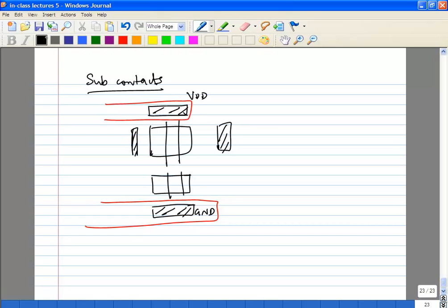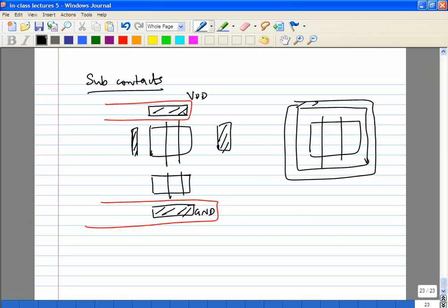However, every process, especially an analog or RF process, will have an RF transistor, which would typically have the transistor and a substrate ring around it. This transistor as a unit will be modeled, including the impedances and resistances of the substrate, everything. So typically if you use an RF transistor, what you see is what you get, because your layout is perfectly fixed. Usually you will measure what you wanted to measure from the transistor itself.